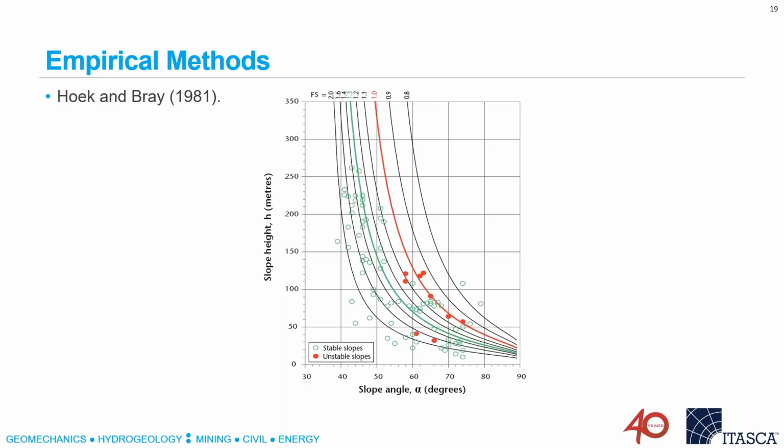The next question is, how do flow rules affect the factor of safety? Okay, yeah, very good. By flow rules, we're talking about really dilation, and how, when we get plastic failure, the associated deformations occur, and that really relates to dilation of the failed material.